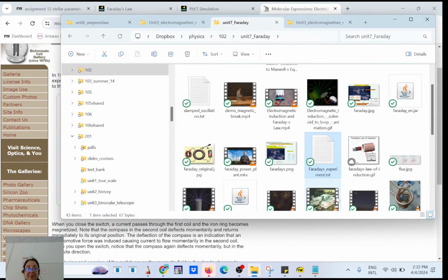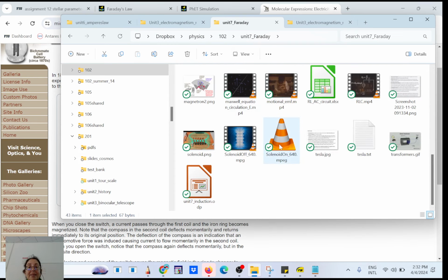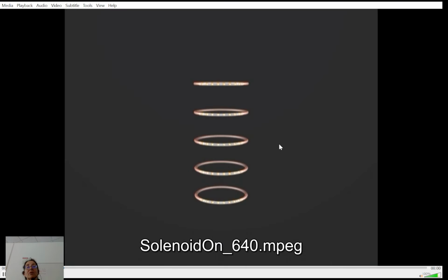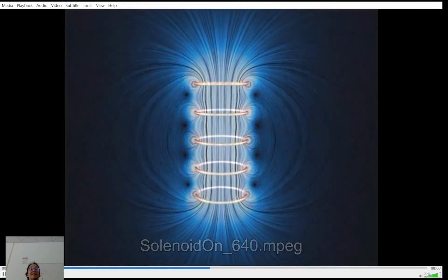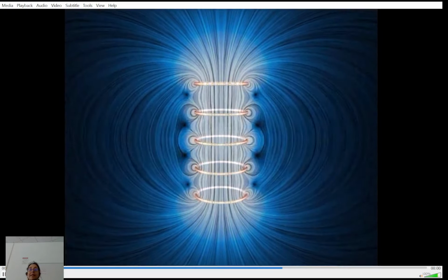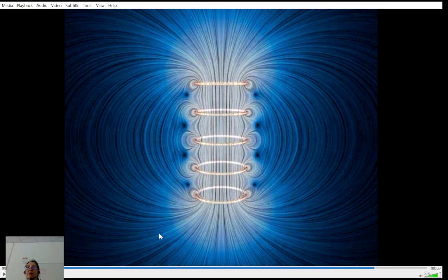So the thing that you need to understand is that with a solenoid, so you have an electromagnet, the magnetic field will expand. It will take time to be fully developed. Why? Because you are taking energy from the power supply and storing that inside the magnetic field.